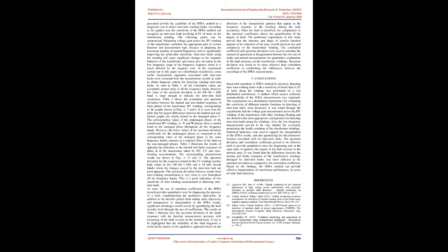For discussion. The SFRA is a method by which evaluation of the transformer condition is carried out by comparing an actual set of SFRA results to reference results. The experiments presented provide the capability of the SFRA method as a diagnostic tool to detect interturn winding faults. According to the applied tests, the sensitivity of the SFRA method can recognize an interturn fault involving 0.2% of turns on the transformer winding. The following points can be summarized.